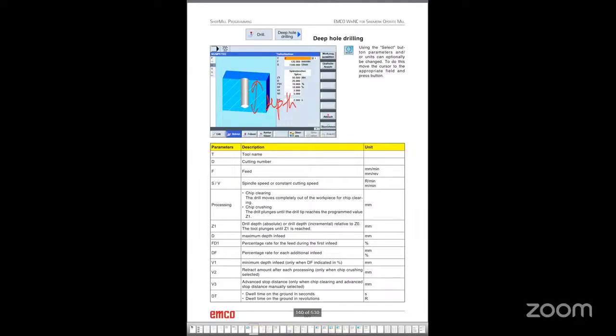So this is the full depth, right? Normally, what will the drill do? The drill will go directly from here, reach here, then retract back to the retraction plane, right? But in deep hole drilling, first the drill will come here, right? Then it will retract back. Then it will go, then retract back like that. This is what is called deep hole drilling.